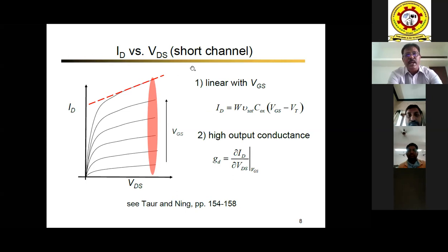So you see the drain current doesn't stagnate anymore. It actually exceeds a certain level, okay? And it doesn't follow the normal conventional mathematical formula anymore. Same is the case now: you see the high output conductance. Obviously, the output current increases, and it obviously contributes to the output conductance as well. Thereby, your output conductance also increases. And these two are not welcoming parameters in short channels.